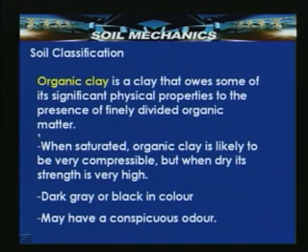So, organic clay owes some of its significant physical properties to the presence of finely divided organic matter. Under saturated conditions, organic clay exhibits very high compressibility, but when dry its strength is very high. Its color varies from dark grey to black and it may have a conspicuous odor.